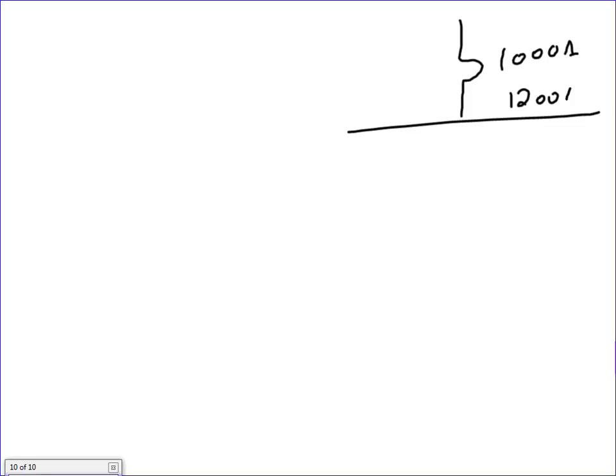So let me go back, guys, to my system. Here's my overcurrent device, 1000 amp, 1200 amp. Here's my ground. Here's my neutral. I need to size the following, guys. I need to size the bonding jumper, and I need to size the grounding electrode conductor.